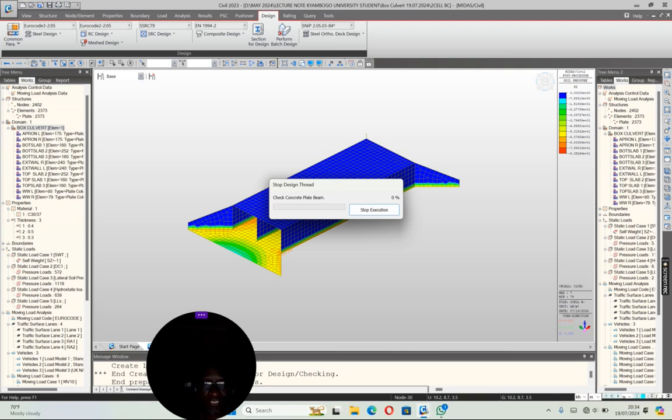The design sequence is very important, something that we normally forget. If you are to have one or two pieces of information to do this design, who do you need here? I think geotech may not, for a box culvert, geotech may not worry because you are going to enhance, in one way or the other, your foundation using rock fill or rubber concrete. But hydrology is very important.